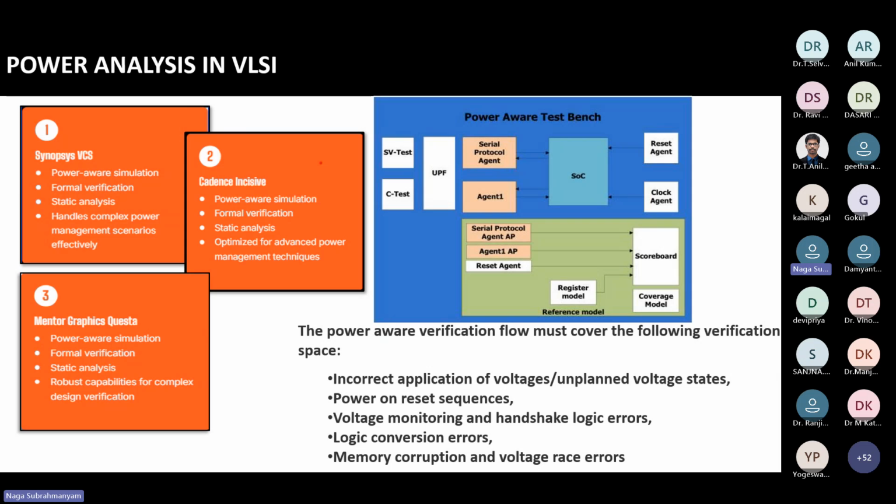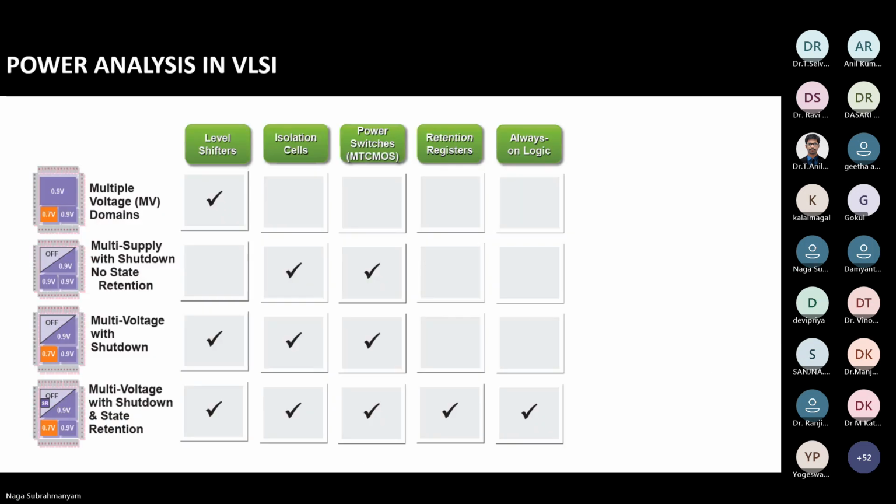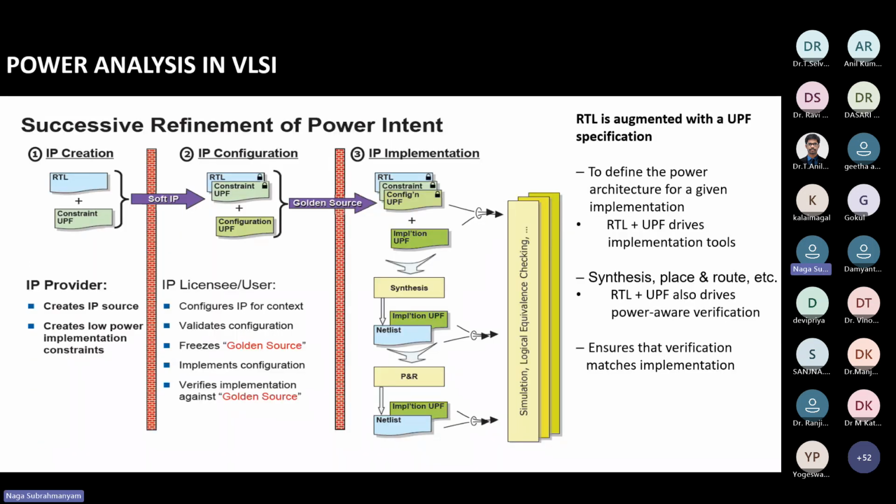As I explained about the test bench yesterday, we will have the same test bench here. We will verify the power management unit, and using UPF we will verify retention cells and isolation cells, all those things. This is how the verification engineer analyzes power in VLSI.